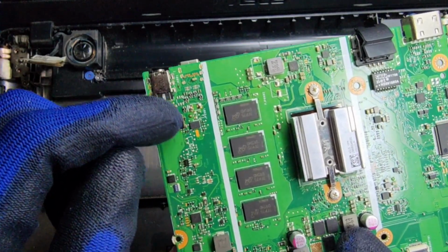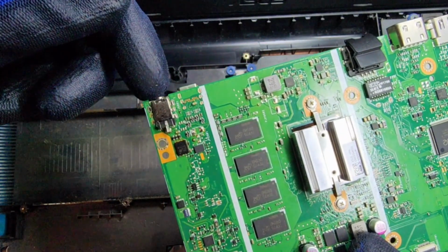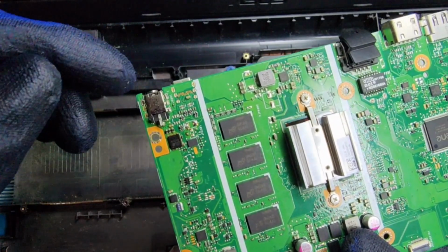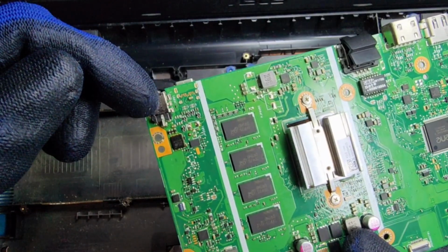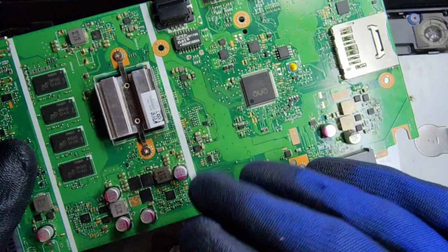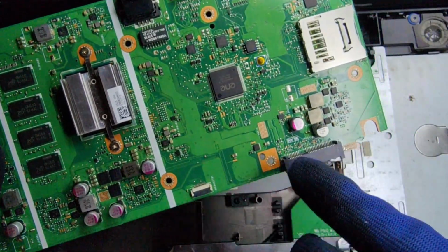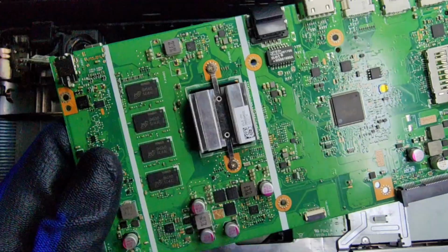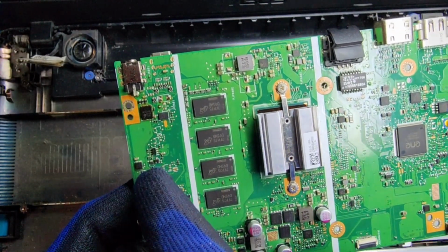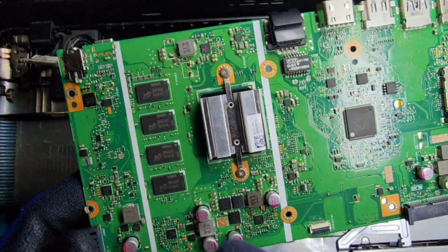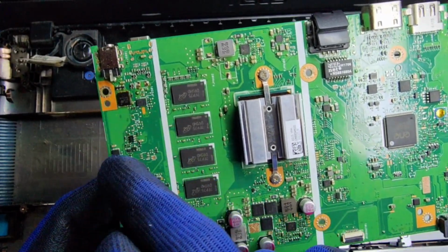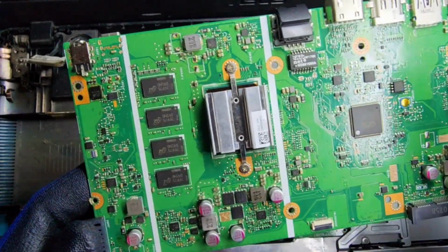But if you short these together, once you connect the adapter, you will get some spark on this DC connector here. That is not actually good. If there's a spark on the DC connector, it will impact all the main power rails. The voltage can ripple, which means it can go high and low, and it can damage the capacitors also in this place here. So the charger IC has a soft start function. Once you connect the adapter, it will take some delay, and then only it will turn on the main power rail here. So these are the benefits of the charger IC and also the first and second MOSFET. So the importance of the first and second MOSFETs is really vast.